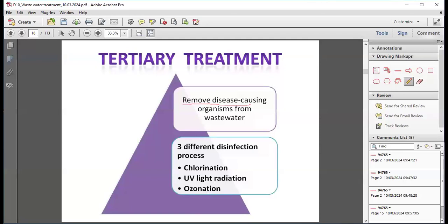It's like a matchbox amount of chlorine that can be added into the well. That's the approximate measurement. One matchbox or two matchboxes of chlorine by weight, we can add into the well.